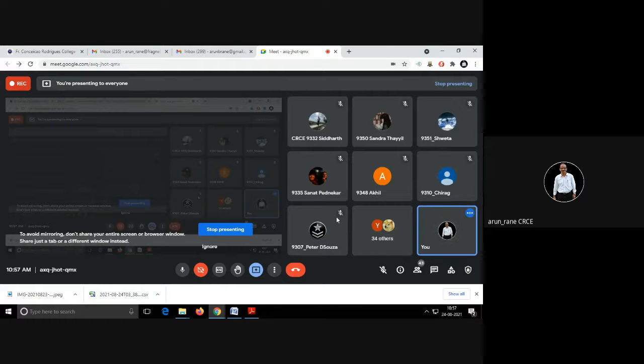The way you heat means what? You can have 2 heaters at a time, you can have 4 heaters at a time, so that the temperature increases all of a sudden. Like we have a room temperature of say 32 degrees Celsius, you can increase the temperature from 32 to 200 degrees Celsius just by having 2 or 3 heaters in just 10 minutes. But that is sudden heating. It's not gradual heating. If you heat suddenly and if you heat gradually, there is a tremendous difference between the properties. And the same thing with cooling. If you cool suddenly and if you cool gradually, there will be a difference in the property.